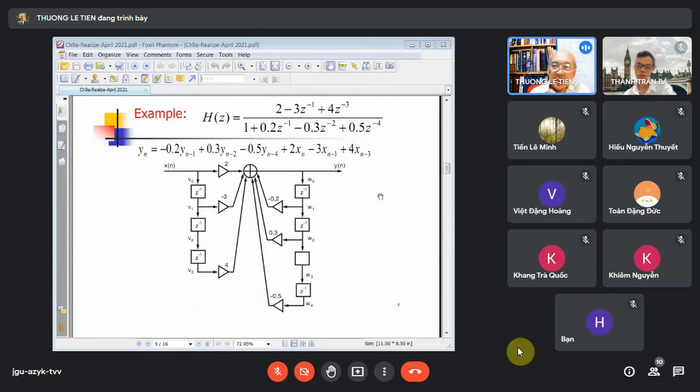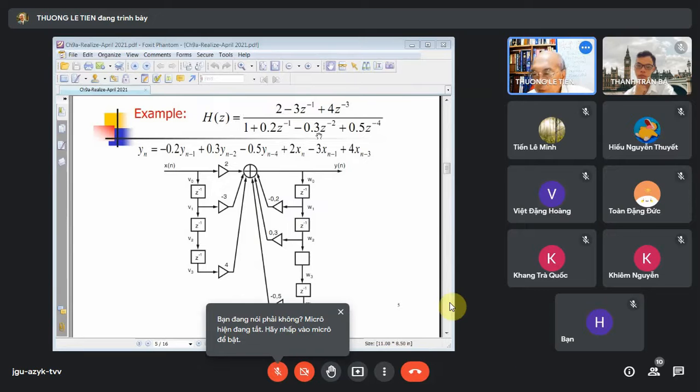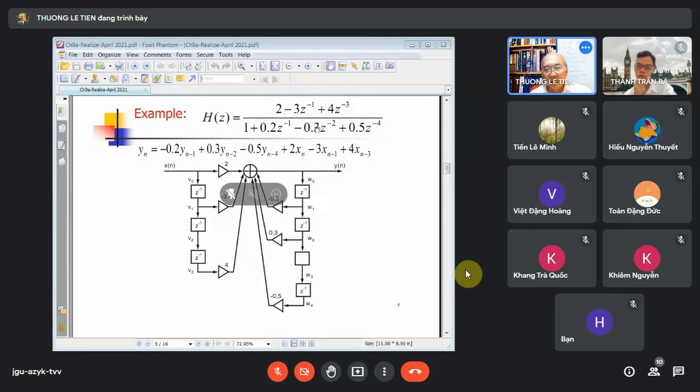Okay. Now, this example, N(z) order 3, D(z) order 4. So we have a fourth order digital filter or fourth order system. Okay. Now we can easily write down the IO equation. Bear in mind, I remind you again, it's no problem when we write n-3 as a subscript, or we can put it in round brackets. Okay, they have the same meaning. When we take this one equal to Y(z) over X(z) and bring it back to the time domain, we can get the IO equation.